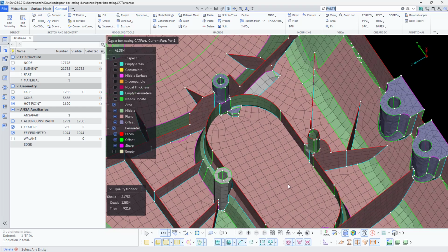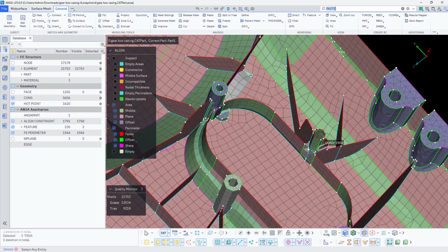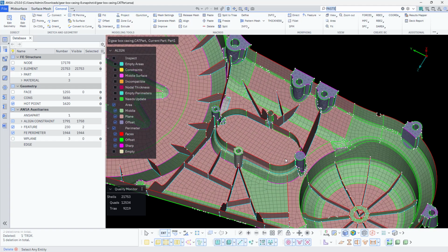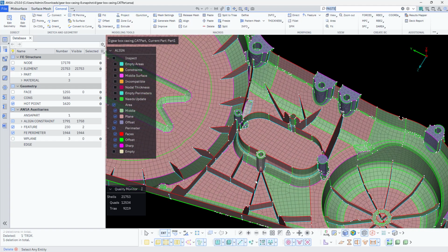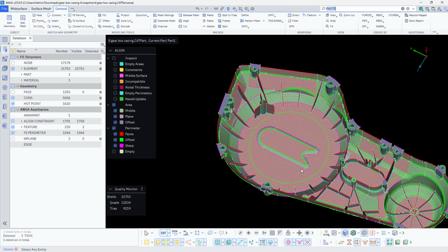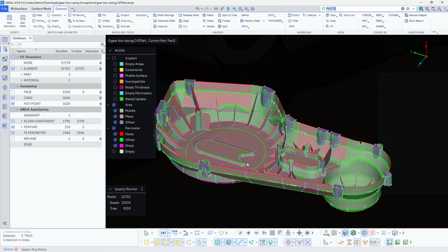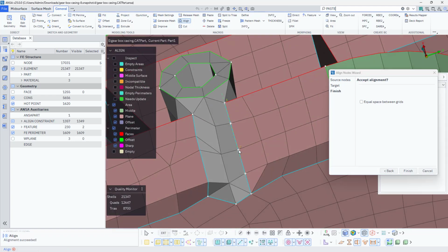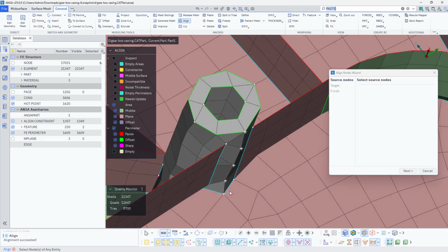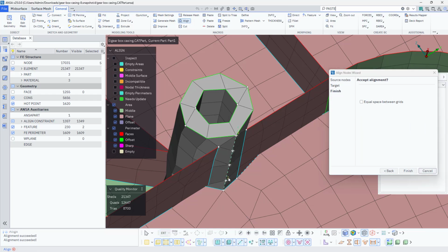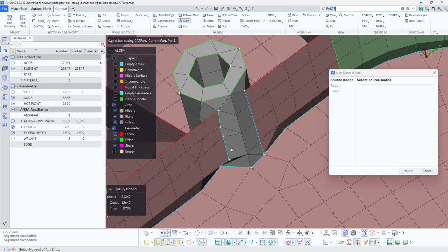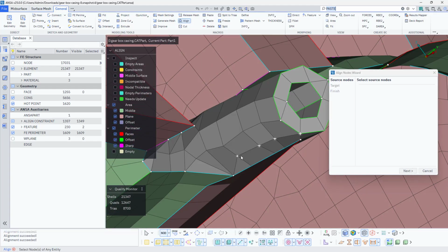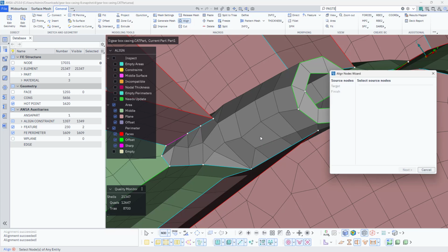Okay, now we'll try to fix these mounts. So what I'll do is I'll try to use some ANSA tools to fix them. Okay, so this is the mount. I would like to first align them properly, so I can use advanced tools. Right now I'm just fast forwarding this one, so everyone knows this align tool now, right? So I'll just select these grids and just define 2 straight points so that it will be properly aligned.